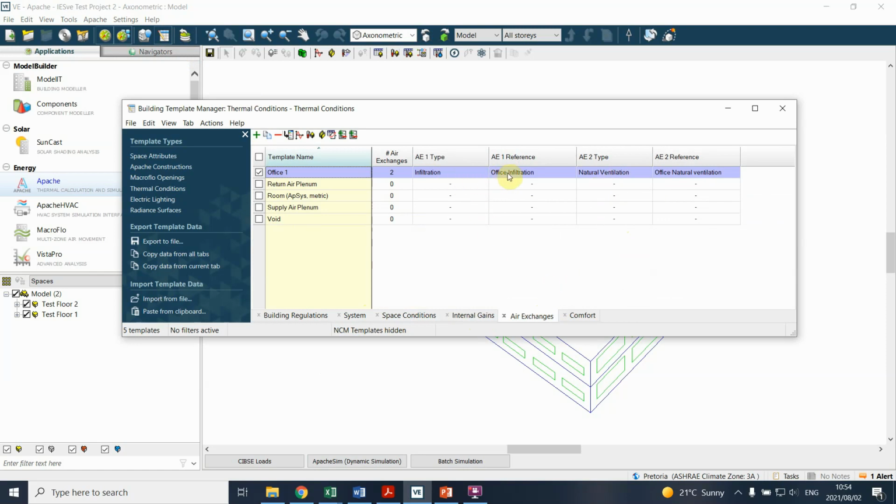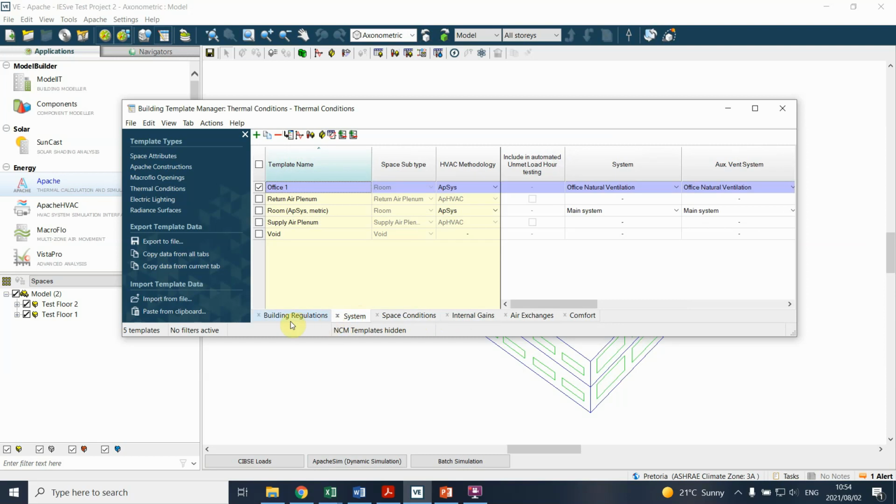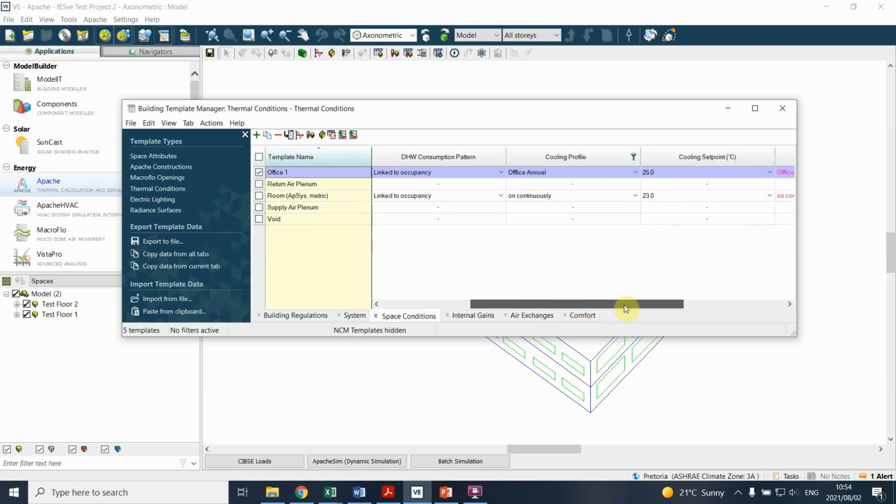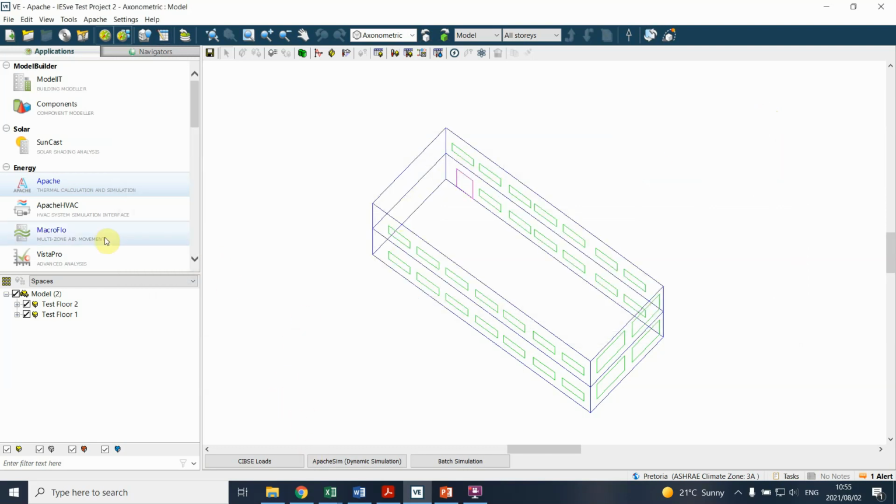Note that we changed it to natural ventilation. There were some previous models where we looked at air conditioning, but the flow is still 7.5 liters per second per person. I haven't adjusted that, and it has considered that in the model. So you don't need to change the flow rates per se, and you can obviously also include these models with an air conditioning system and see what happens then. Again, test it and see whether it works, and if there are any anomalies, then you need to check your model, or you might be learning something from it.